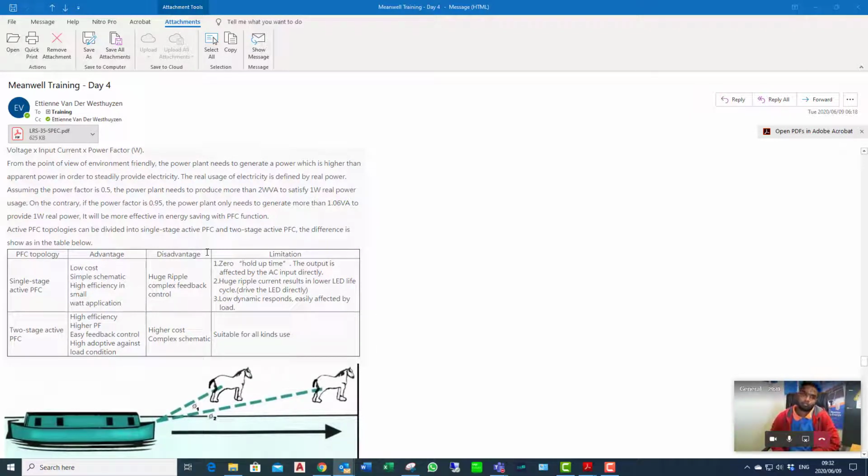Okay, so you always need to make sure that your power factor of your plant, of your power supplies, are optimized. Yes, you're going to be paying more, and I think we'll look at the values of the difference between an LRS, which is your cheap version, your RS, which can handle higher temperatures, and then you've got your power factor correction portion, which is even more.